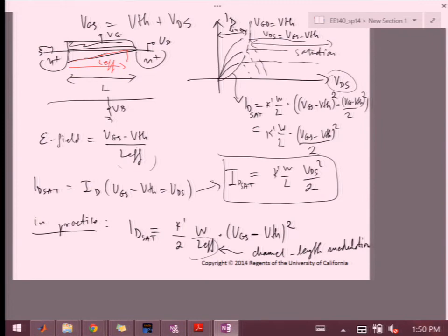But what caused that voltage to change? If you look at the overall transistor, I have only 3 terminals to move. What can cause that internal base collector potential to move? When the transistor was on, we said VBE was pretty much 0.7. So whatever you do to other terminals, it stays like that, right? So all the voltage drop gets dropped across base collector. So if I change the collector voltage, most of the voltage drop is across base collector, right? And that's what's causing it to move.